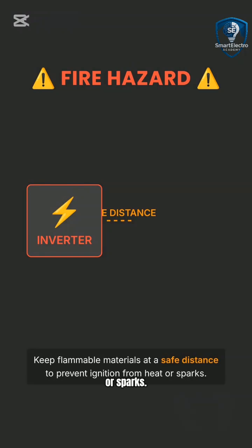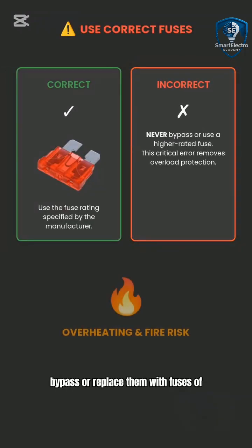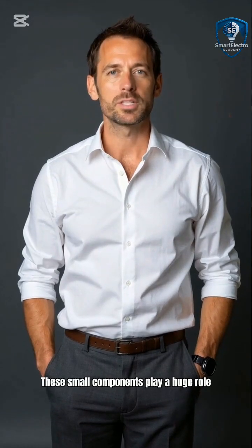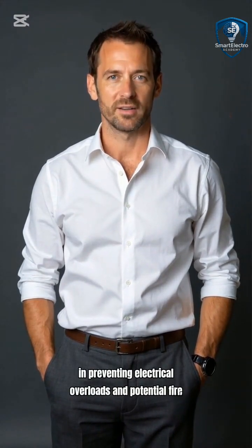Using the correct fuses is vital. Never bypass or replace them with fuses of a higher rating, as this can lead to overheating and fire. These small components play a huge role in preventing electrical overloads and potential fire incidents.